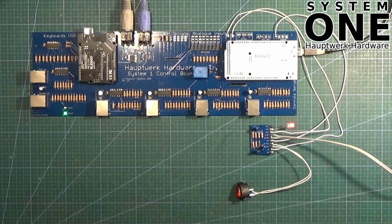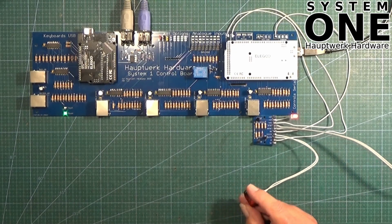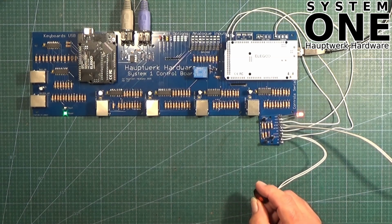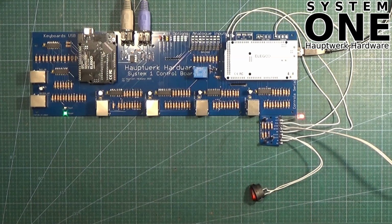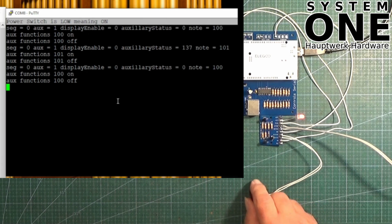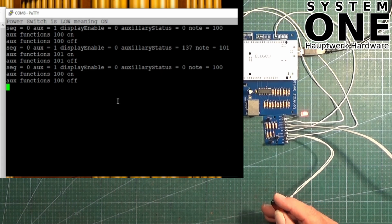So let's go back and look at what happens now from a MIDI perspective when we turn it off, because you'll remember when I switched it on, we said that there was no MIDI sent. So if we come back to the computer and look at that at the top, power switch is low, meaning on, but then the MIDI that we see after that was much later on. That was the 100 for the light to turn green. So when I switch this off now, we'll see on the computer what happens.